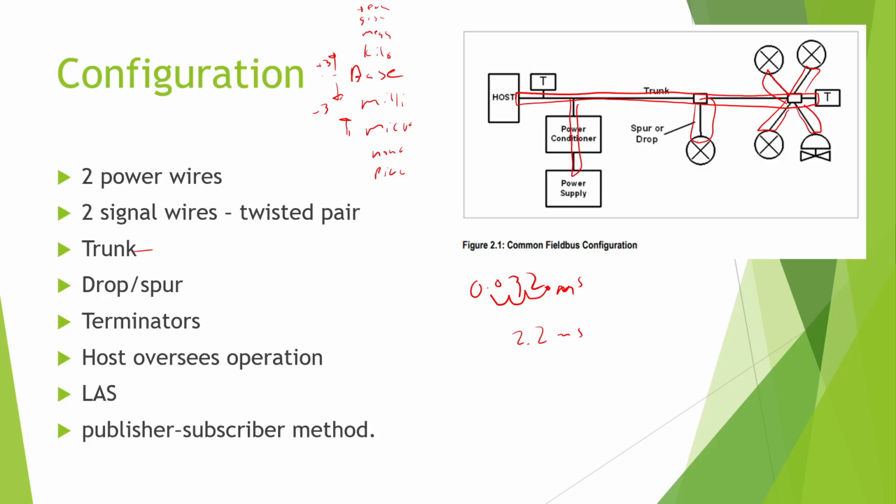Now, again, different communication protocols may have some different specs there, so there are going to be some tweaks to this. But as I said, Fieldbus is a group of other protocols, a group of other specifications, not a great term, but protocols on their own. So I just want to say this is all going to be taken with a bit of a grain of salt. Terminating resistors are still going to be there. Spurs are still going to be allowed, but maybe the max distance will change.